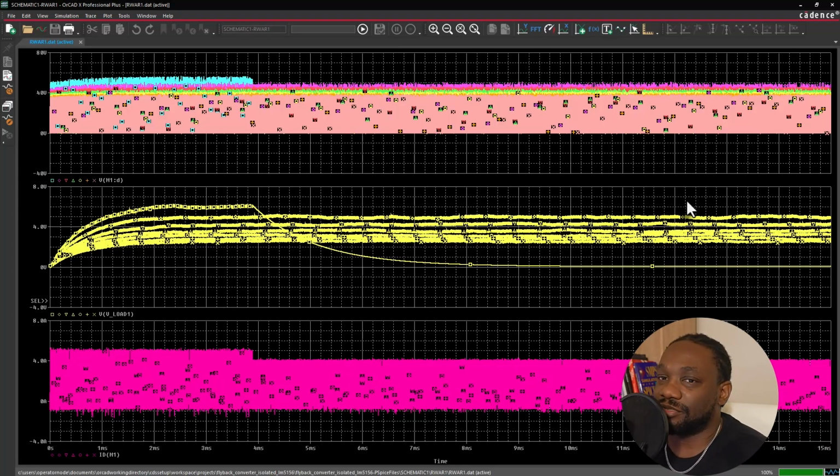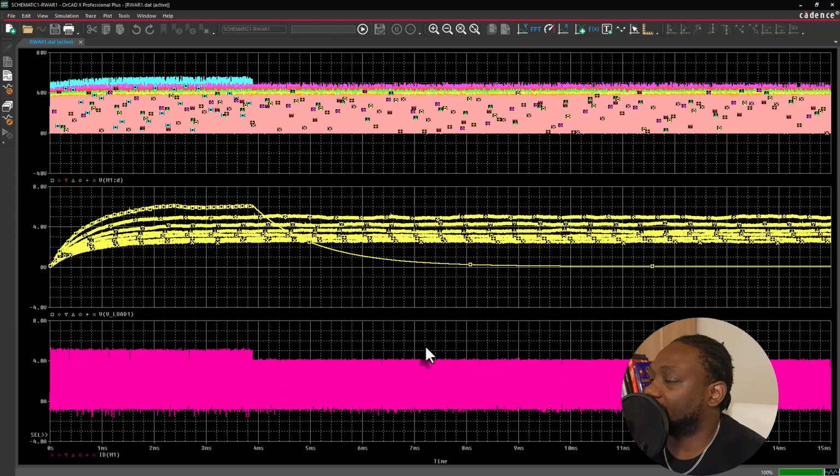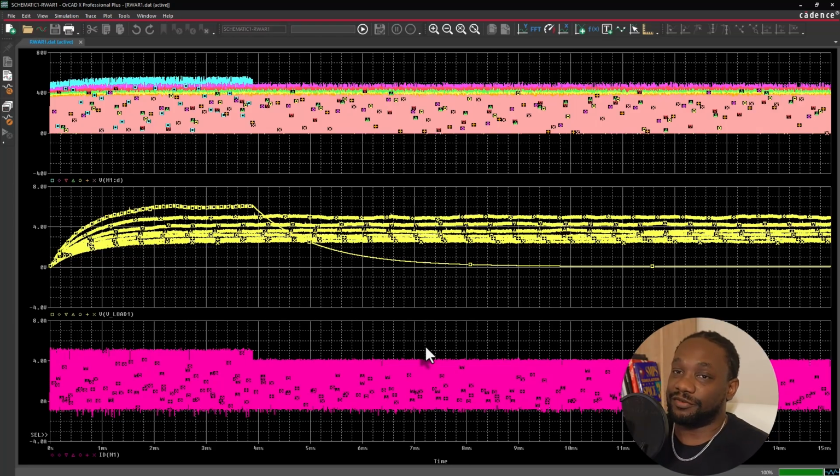You also have options for power consumption and whatnot, and analyzing the power on that. But see that this is powerful. This is the power of using parametric sweep. And how would you even know which components to do a parametric sweep on? Well, that comes from your Monte Carlo analysis and your other analyses like worst case.